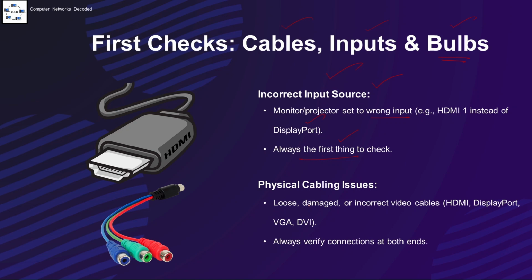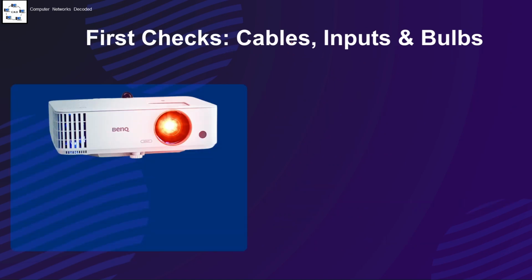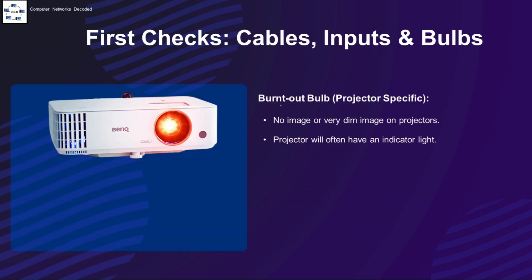Then check the physical cabling: loose, damaged, or incorrect video cables, for example HDMI, DisplayPort, VGA, and DVI. You need to check that the cables are not loose, not damaged, and are the correct cable for the correct port. So always verify the connection at both ends.